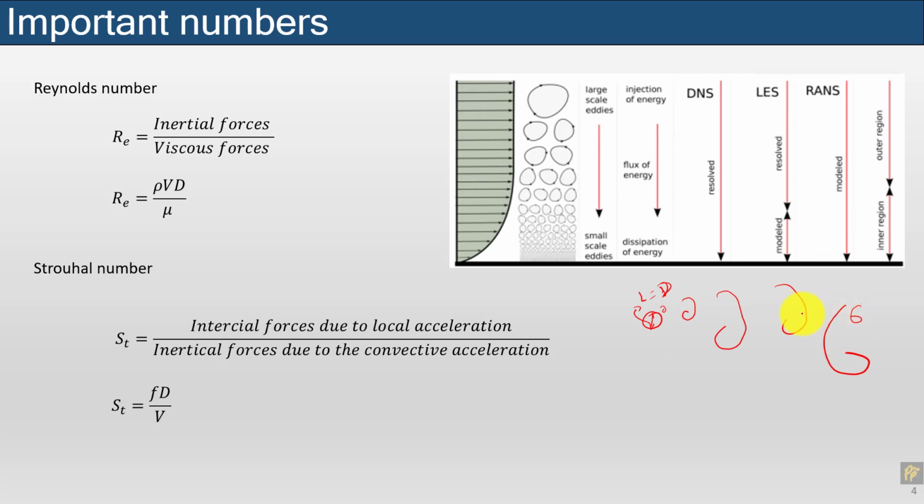At the same time, if you take a look at the turbulent flow, we observe that there are multiple scales. Eventually all this energy will be dissipated and changed into viscous dissipation, and eventually into heat energy. In the case of turbulent flow, we have a lot of vortices, a lot of vortical energy. To resolve them, we cannot solve them with URANS. RANS is steady state, and URANS is the unsteady Reynolds averaged Navier-Stokes equation. So for turbulent flow, we are not solving the turbulence fully.